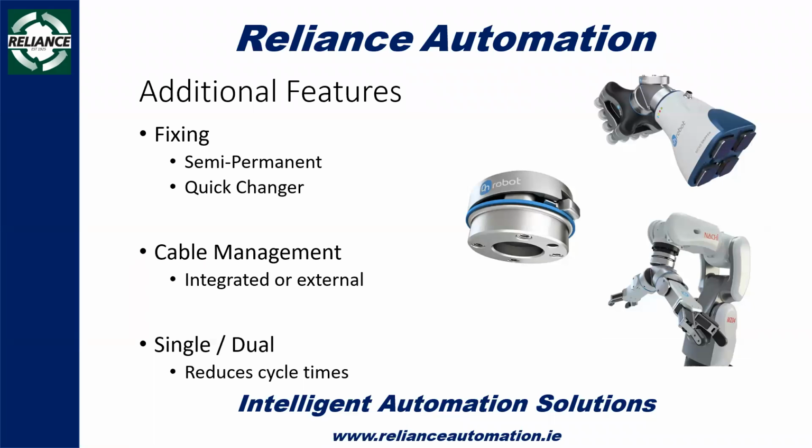Once you've selected the type of gripper that is suitable for your application and the actuation technology that's going to be most beneficial to you, there are a number of additional features that you can have a look at, such as the actual fixing of the end effector to your robot. If it's an application that's going to stay the same 24/7, 365 days a year, semi-permanently fixing it by bolts is perfectly adequate. Whereas if it's something like a mobile robot that you're moving from application to application around a factory, you don't want to be taking off those bolts every time you have to move it around. Something like a quick changer, a simple release of a button to change the tool heads to a different application, may be more beneficial.